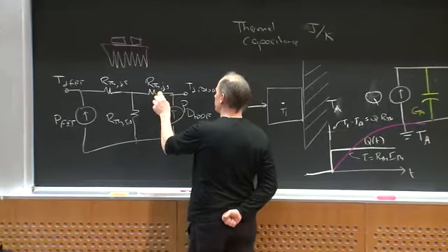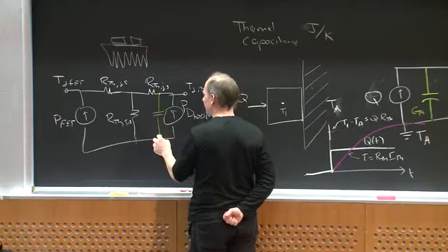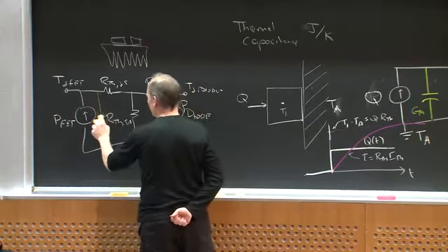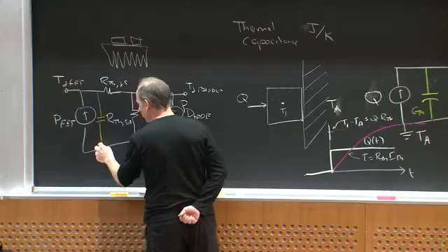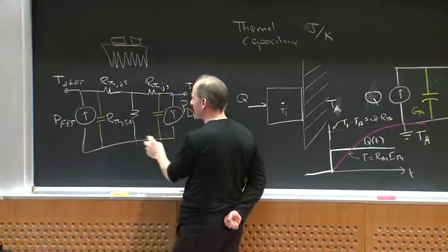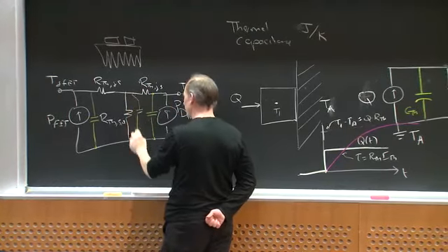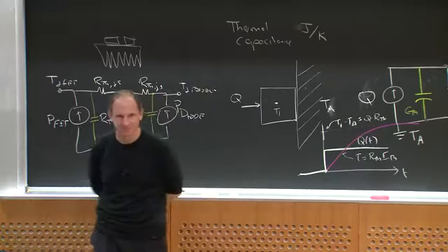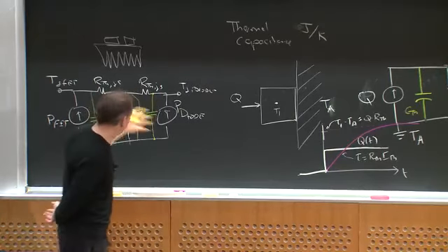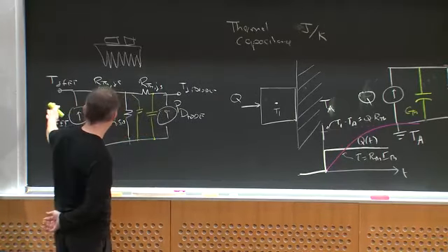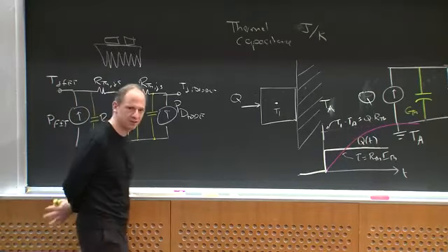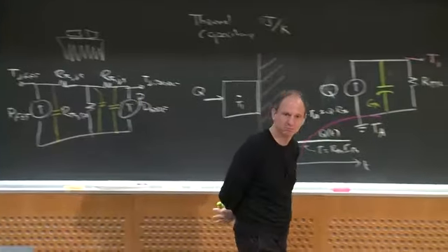So this device package might have a thermal capacitance, and this device might have a thermal capacitance, and I ought to place it to the reference potential. The heat sink might have a thermal capacitance, and then I get a higher order thing. Now, when I get to t equals infinity and I have some step response here, it all settles out to the same steady state model. Okay?